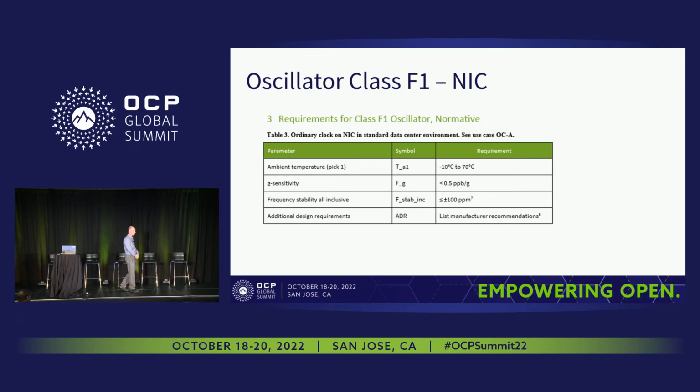As applications get developed with tighter requirements going below a microsecond, you would need to bring in a TCXO. But we're waiting for applications in the software layer to take advantage of that, for operators to introduce services for time-sensitive applications. So for oscillators in a NIC, an XO, the largest source of error is going to be thermal drift, so temperature variation or temperature gradients. That's going to be the largest issue.